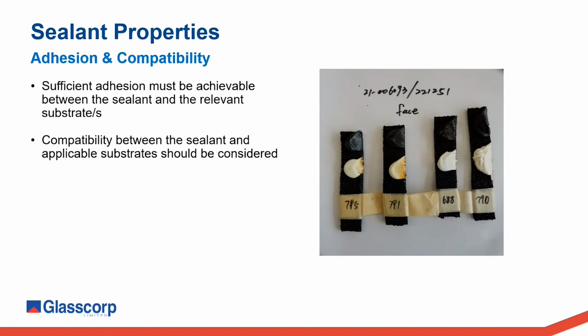While we normally consider sealant adhesion first and foremost, we cannot ignore compatibility. So when incompatibility between a sealant and a substrate, or between different sealants, is present, it normally presents as noticeable sealant discoloration in minor cases, which may be no more than an aesthetic issue. In severe cases of incompatibility, the mechanical properties of the sealant may be affected, resulting in sealant hardening or eventually adhesion loss.